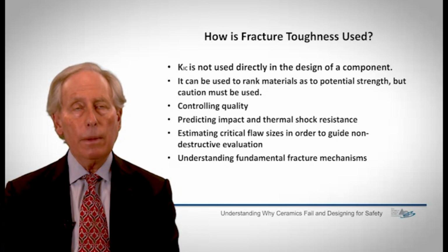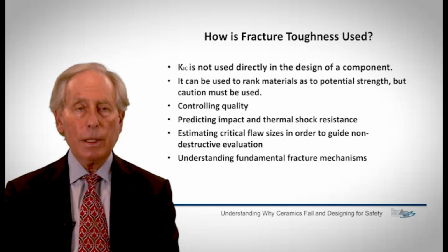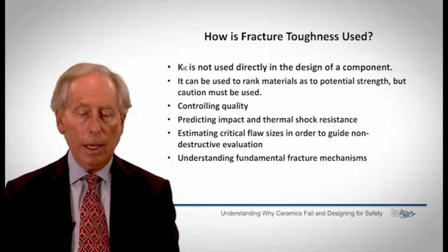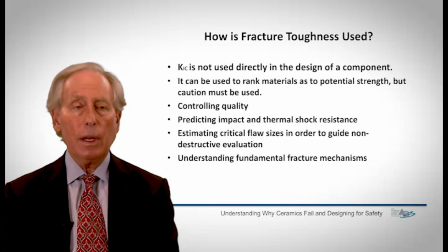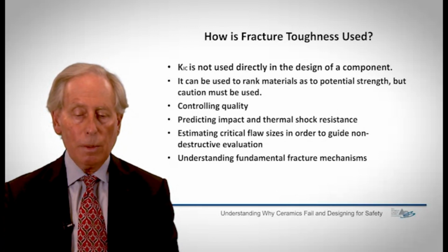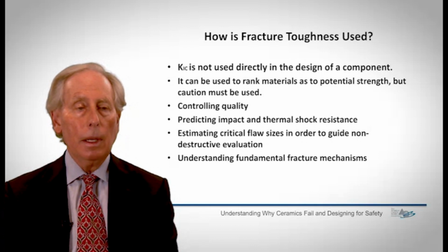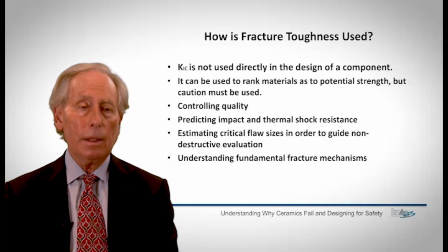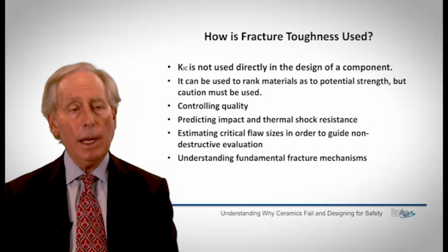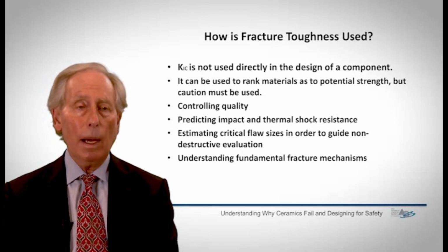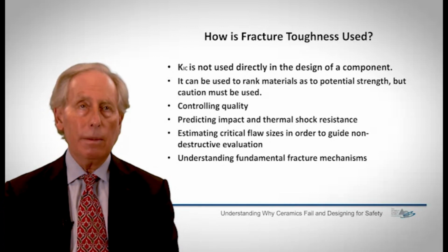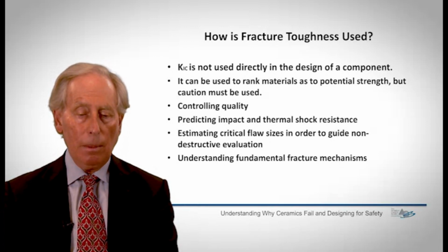For the most part, if fracture toughness increases, strength increases as well. There are cases in some materials in which this is not the case. There can be even an inverse relationship between fracture toughness and strength. I won't talk too much about those, but just to make the point, you can rank materials, but it's not absolutely certain. You can use it to control quality. Can I tell that the material I made today is the same I made yesterday? Well, fracture toughness can be an easy way without doing a lot of strength measurements to determine whether I've made a material that's representative of the whole batch of material that I need to sell.